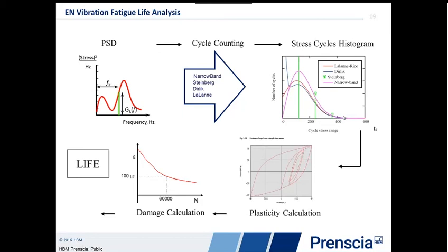And in StressLife, that's perfectly fine because I can take each one of those bins in the histogram, take its magnitude, mean stress, and calculate fatigue damage and sum up the damages. In StrainLife it becomes far more complex because we're going to take the linear elastic stresses or strains, and we're going to do plasticity on them. We're going to basically do a plastic correction using Neuber, Hoffmann-Seeger.